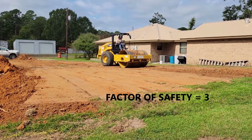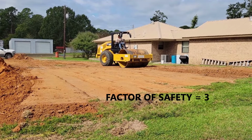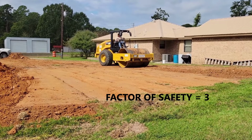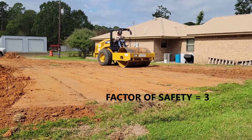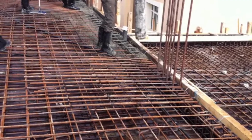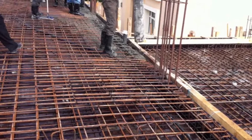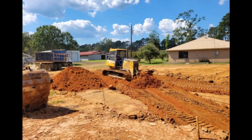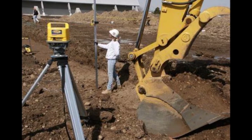Why did our structural engineer include this factor of safety of 3 in his design? Because there may be some construction inefficiencies during the construction of the building pad and the concrete foundation that may hinder this design's overall strength and durability. Items like missing reinforcing steel in the slab, inadequate slab thickness, improper backfilling procedures used in the building of the pad, and not excavating to the required depth to remove the unsuitable soil.